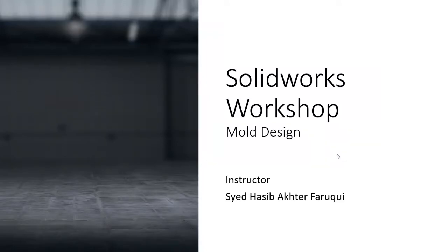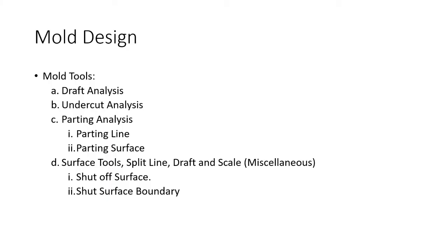Hello everyone. In this week of SolidWorks workshop, we'll learn the mold design toolbox. In this week's tutorials, we will learn the use of the draft analysis tool, undercut analysis tool, and parting analysis tool. Then we will also learn some of the tools that we already have covered in previous sections, but in terms of use in shut-off surfaces and shut-off surface boundaries.